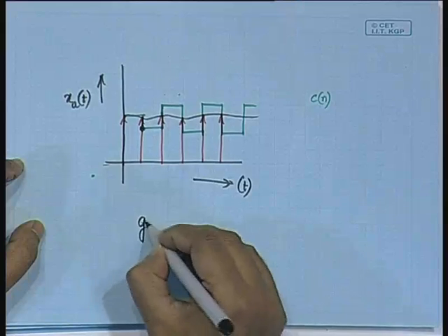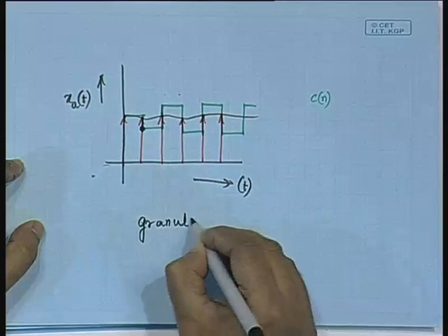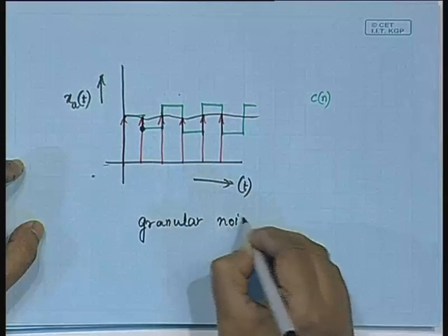If delta is large, then for the uniformly varying signal portion, we are going to have a good amount of estimation error, and this error, anybody knowing? It is called the granular noise. So this results in what is called granular noise.